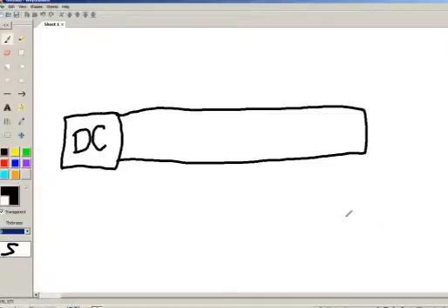Now, I'm sure most of you are experienced enough to know that if you have a dead shorted cable pair and you know the gauge of the cable, you can convert that ohm reading into distance, right? That's called ohms to feet. Well, I'm going to give you that part.